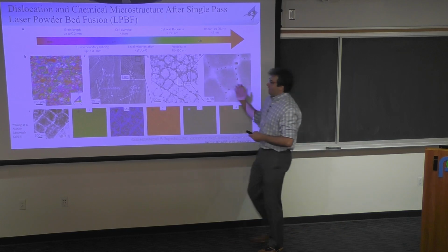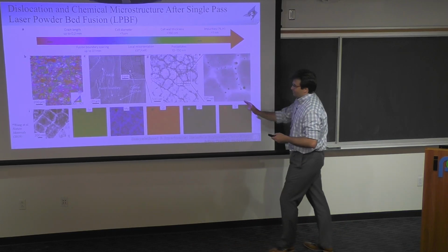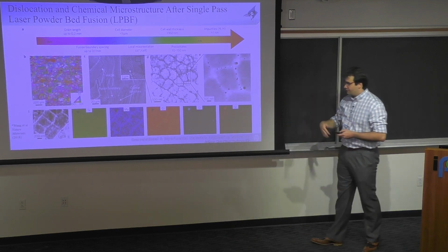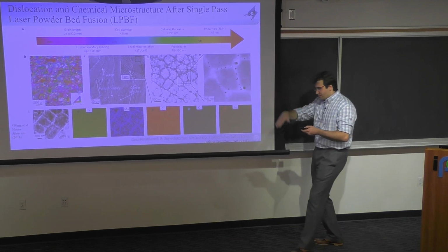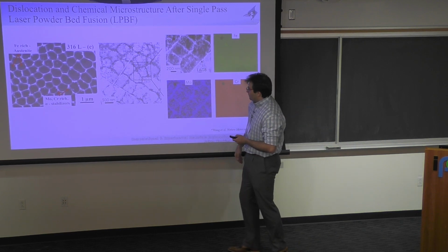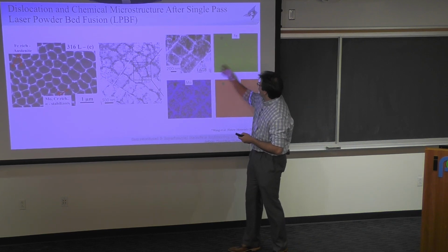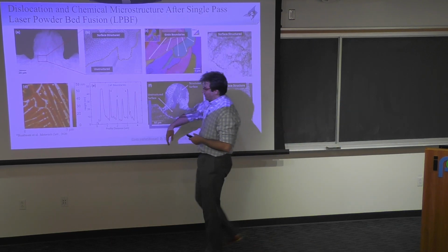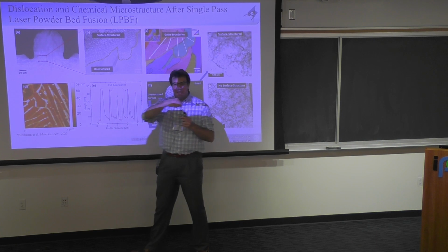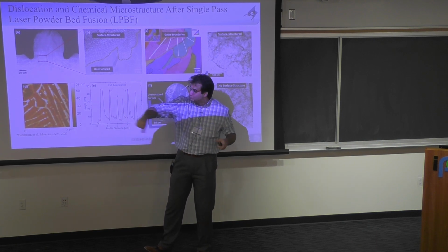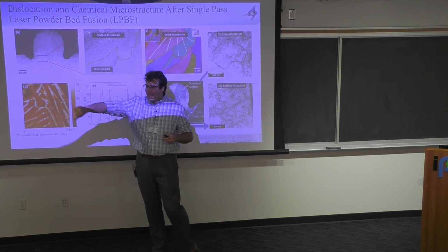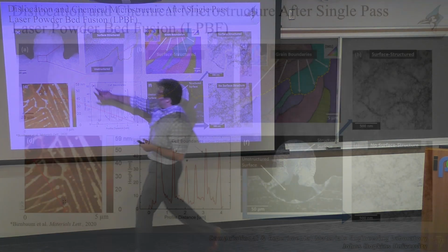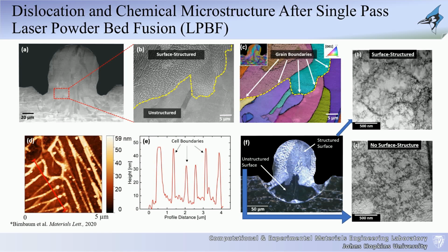So now, this was actually a complete part that was developed. I believe you actually do multi-layers of depositing materials. Again, this is just a close-up, and you cannot really see it from this projector, but nevertheless, it's the same idea. But then our collaborators at the Navy actually did a single pass of a laser. So they put a powder down, walk just with one laser pass on the sample, melt it, and it solidifies. And this is basically what you're seeing. That's the melt pool that solidified.